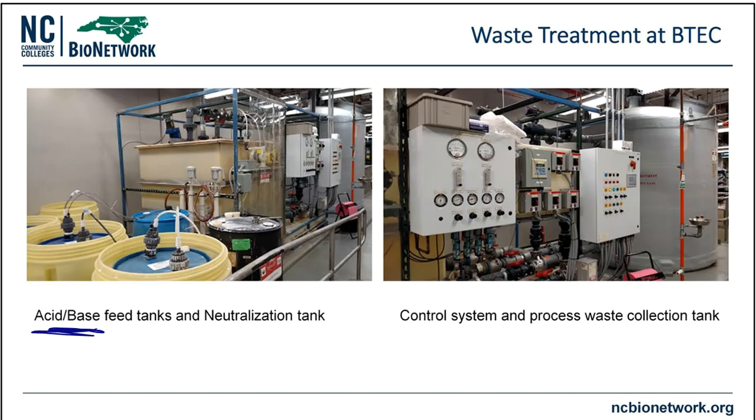Then on the right-hand side, you're seeing these collection tanks, and those collection tanks are going to be collecting the waste that we've either treated or that we need to treat, and then what happens after that, there's an SOP for that, literally. So as far as neutralizing these systems, that is a pretty common kind of setup, and acids and bases are commonly used in those waste treatment processes for that reason.